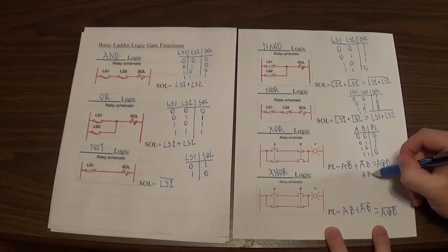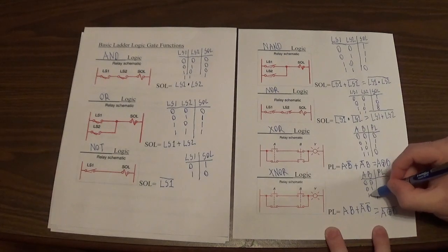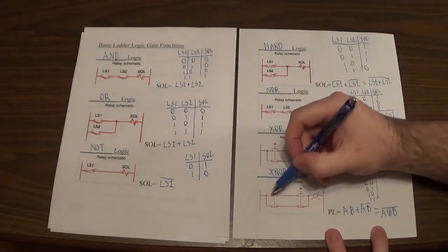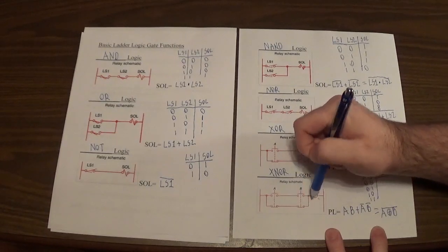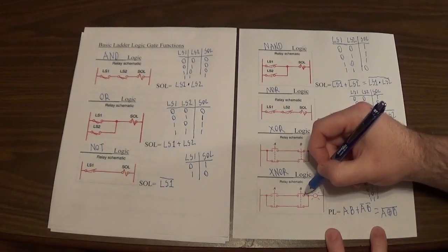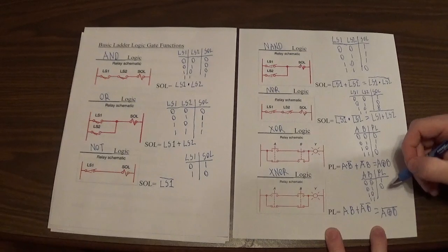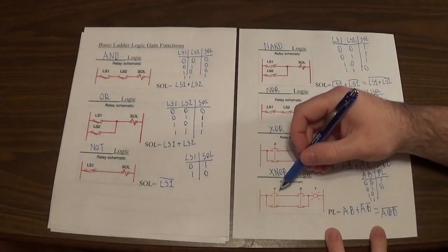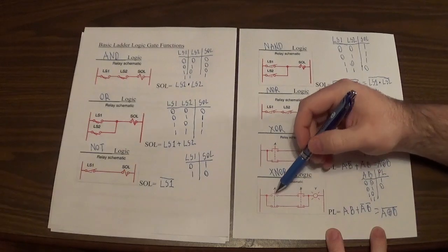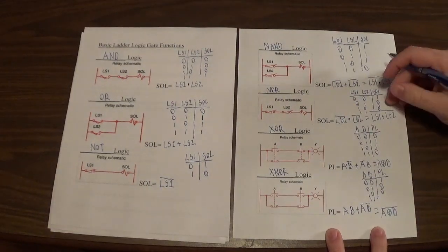So if we look at our table again, if I don't push anything, the pilot light is on. Why? Because down here on this bottom line, these are both closed, so the pilot light is going to be on. If I just push B, that's going to open this down here and close this up here. So now there's not a complete path through the top or the bottom line, so the pilot light is off. If I let go of that and only push A, then B is open, A is closed, so no path for current flow, and A is open down here, B is closed, so no path for current flow, so the output remains off.